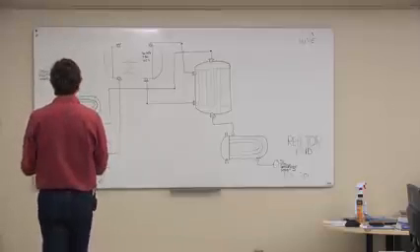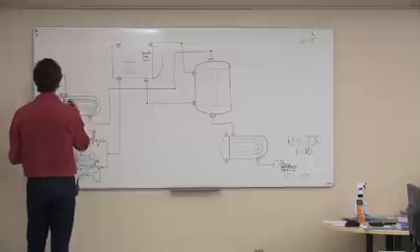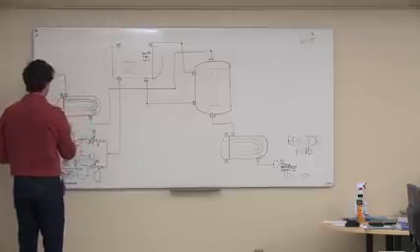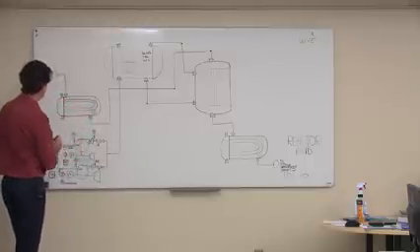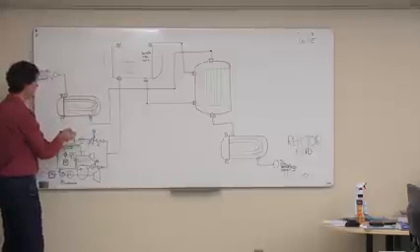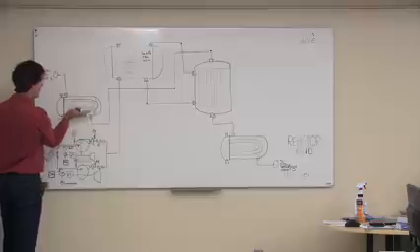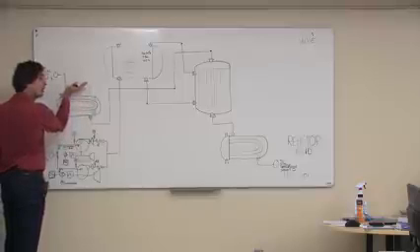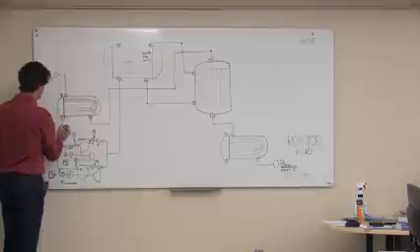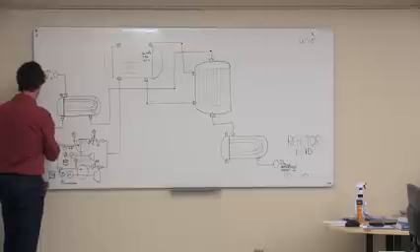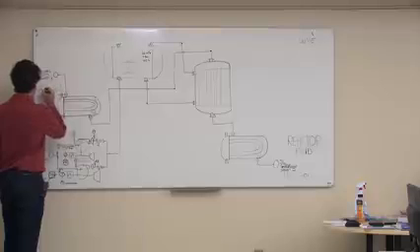Cooling water, yep. Yep, we need some cooling water. So I think because it's a U-tube and it's horizontal, what I want to do is bring my cooling water in the bottom of the heat exchanger so it floods upwards and pushes any air out of the heat exchanger. So I'm going to do it that way. And I'm just going to go right off the sheet here.